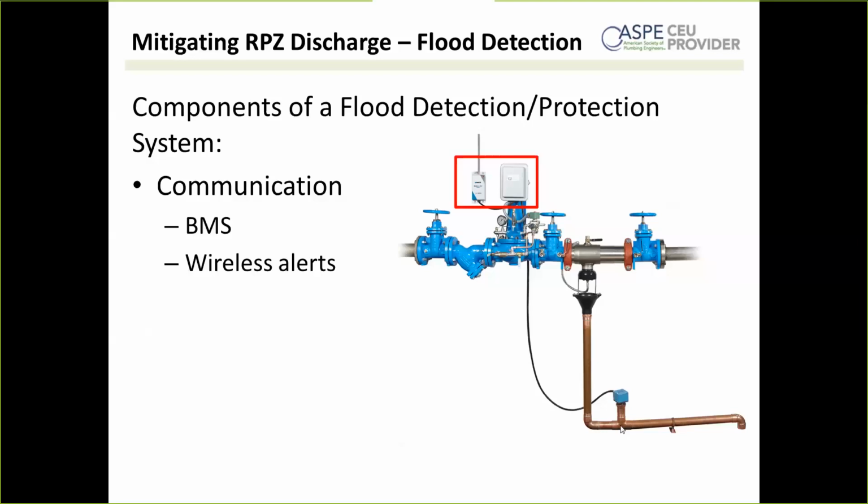Do you have any thoughts about strainers at every backflow device in the building versus maybe just at the device for the building? Right. So this is, do I want one big strainer right in front of the main backflow, or do I want one in front of every single one? I would love to see one in front of every single backflow.